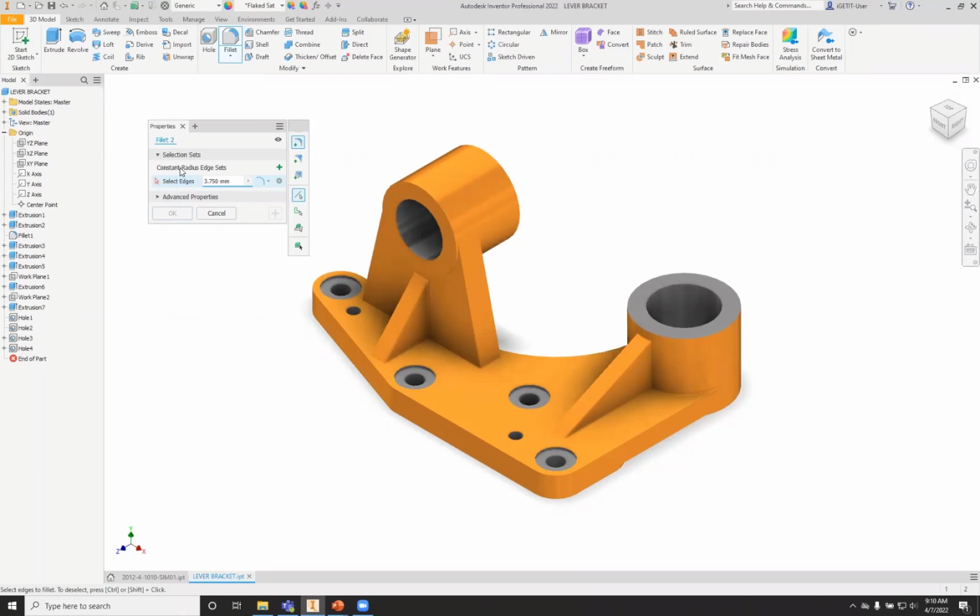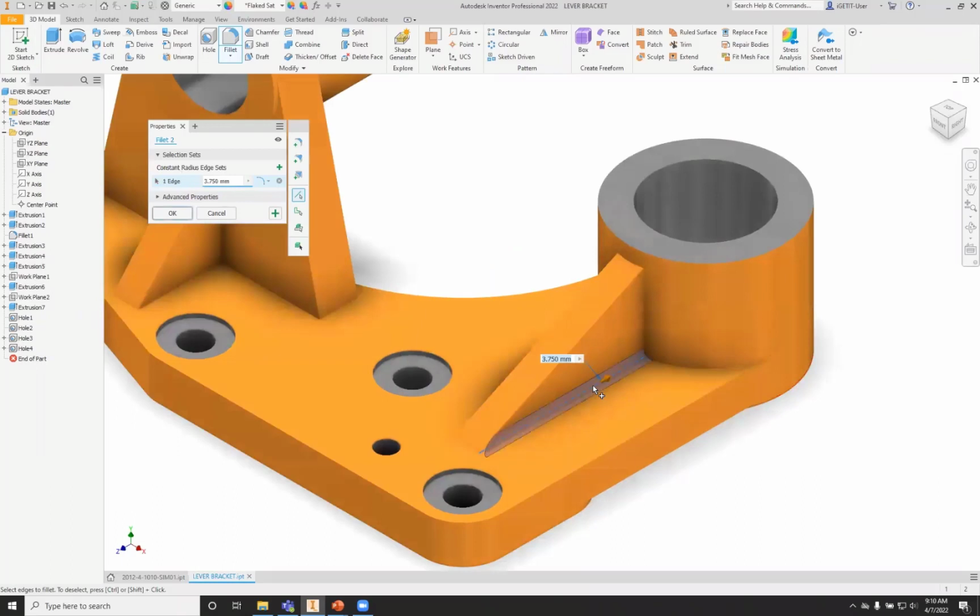So we're starting with a constant edge fillet. If I select an edge here in my model, you notice, as we're kind of used to, we have a preview with that preview turned on. Again, if we turn it off, you still get a basic preview, but you don't get that 3D model preview of what the fillet's going to look like. We still have the manipulators on the model, so we can change the radius here. And additionally, within the panel, for edge 1 that we selected, we can change the value within the panel here as well.